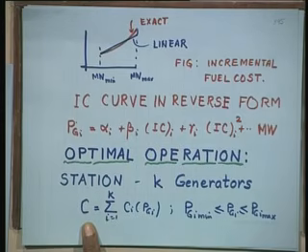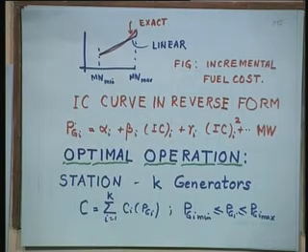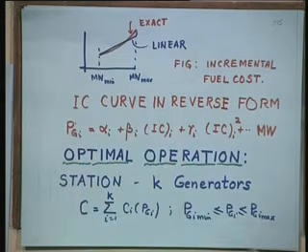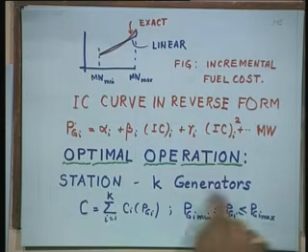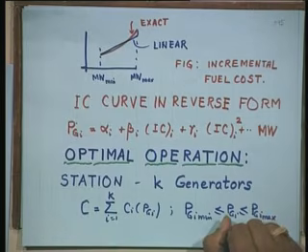So, the equation to be minimized is capital C cost equal to sigma i equal to 1 to k Ci Pgi, subject to, again you have seen the megawatt minimum, megawatt maximum. Pgi has to vary between Pgi min and Pgi max. I now do not have to explain this constraint equation. This is inequality constraint.